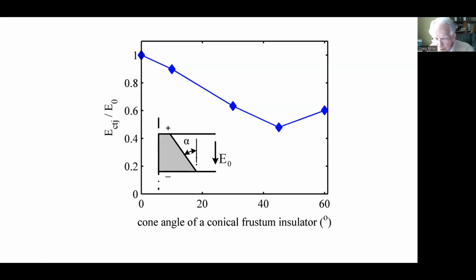Again, calculations of the behavior of electrons, actually making plots of the trajectories of the electrons emitted from the cathode triple junction, again indicated the advantage of positive insulator angles and predicted the lowest flashover voltage for angles of 5 to 30 degrees. Again, as I mentioned, representative results for tests with cylinders and the positive and negative 45-degree cones indicate the effective cone angle is greatest for short voltage pulses. But again, the modest increases seen for power frequency can still be significant.